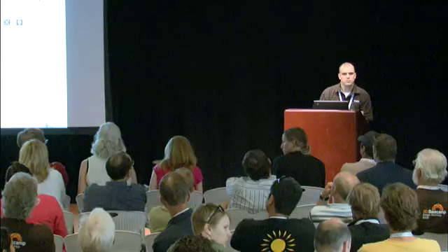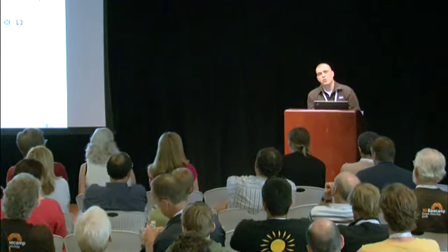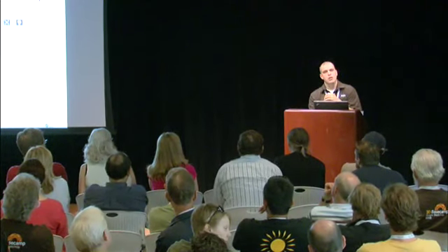Once you're done modeling your component, you have a series of components nested within it. Is there a way to merge them all together, or just create a single component, so that by the time you finish out your scene, you don't end up having several hundred pieces that are components, where in reality you may only have like 6? So, in your question, you're suggesting that, say, for example, this chair, once we're done with it, we explode it and then make it one component. That is the only way to do it, but even though you do build quite an extensive library, I still recommend that you don't explode it.